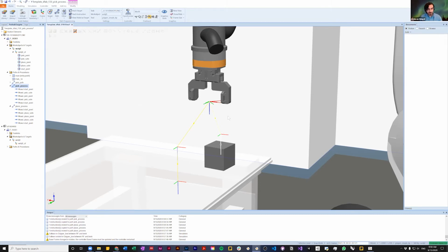So in the process of doing these robotic workflows, we are doing this a lot. We always make sure that, for example, the robot gets to that target, and then waits for an amount of time. And then we do some extra things in the background. For example, open or close the gripper, and then continue moving around.